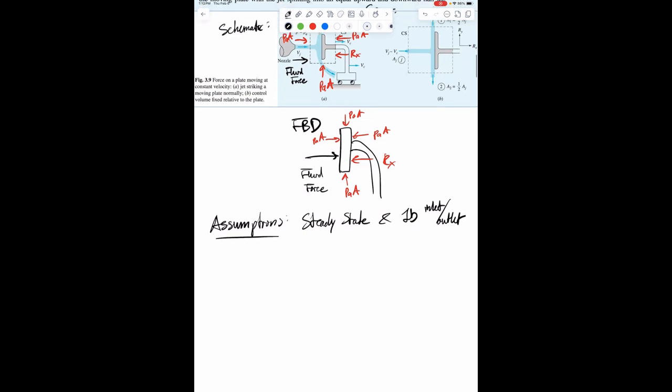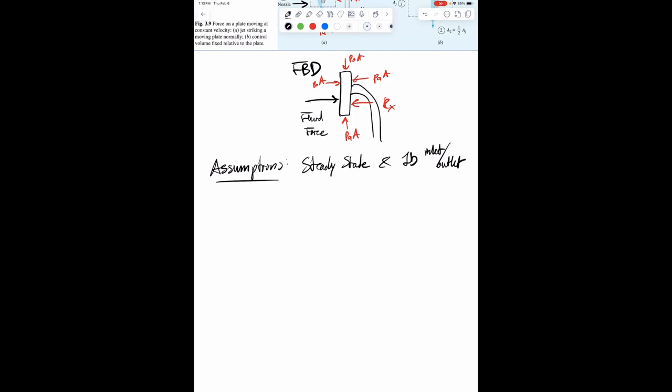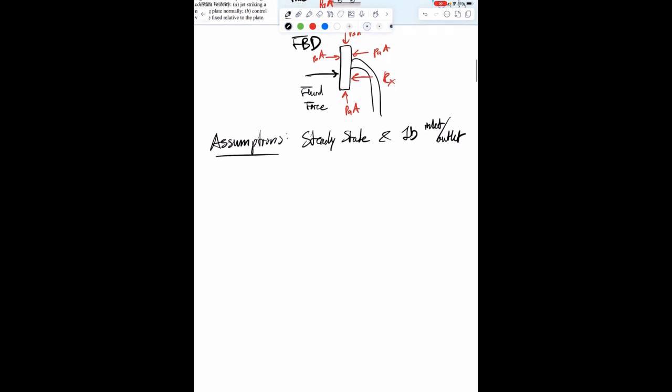Okay, let me quickly jump back and talk about Reynolds transfer theorem, because that's usually where I like to start. We know that the definition of force is time derivative of mass times velocity, or your momentum. It's the time derivative of your momentum. That's what force is. So either you do time derivative on velocity, which then you get mass times acceleration, or the time derivative is applied to your mass, which then gives you mass flow rate times velocity. So either or, tomato.